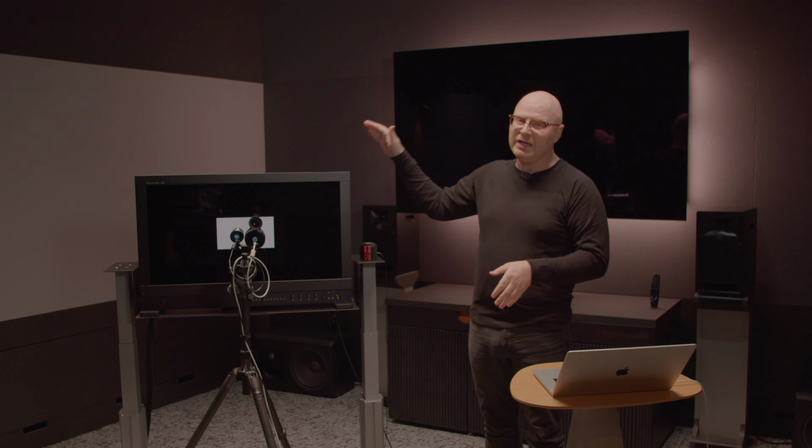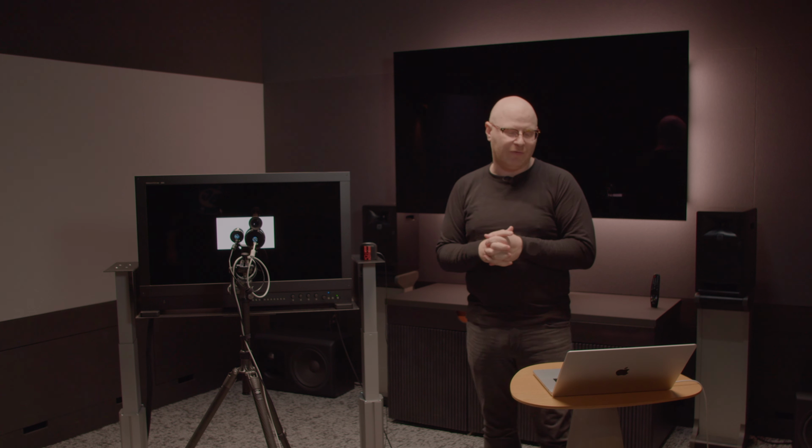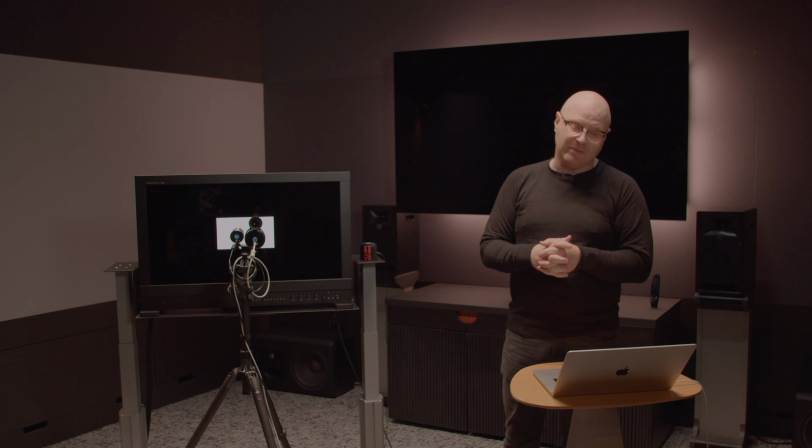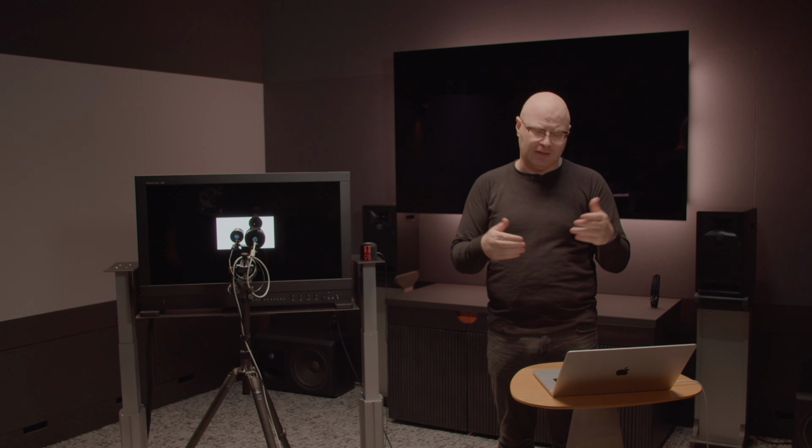If you were just using the internal test pattern generator, you'll be able to white balance, you might be able to target a luminance level, but you're not going to be able to validate that EOTF curve and make sure that you're right where you need to be. And as you can see, when I brought that luminance down to about 920, we were tracking low on the EOTF and getting slightly larger numbers.